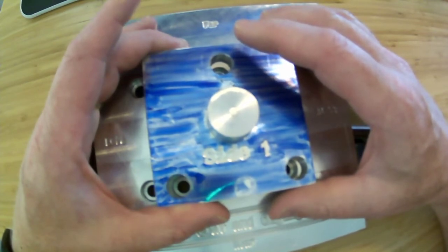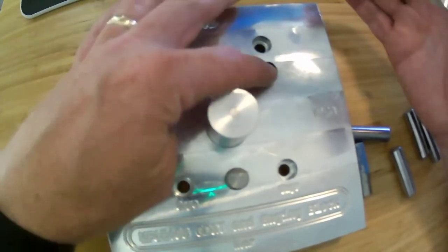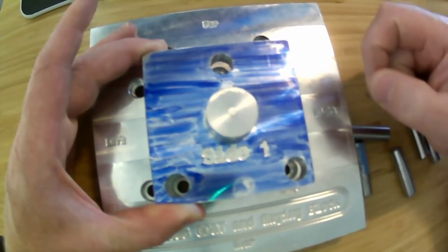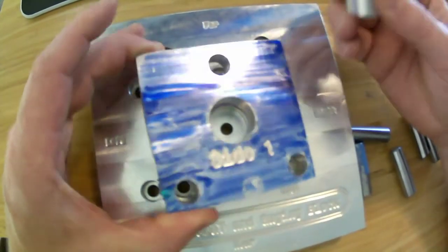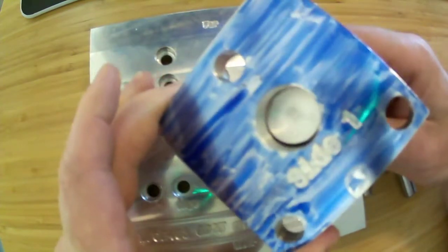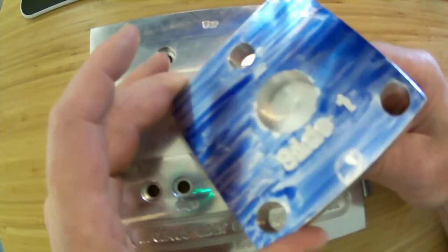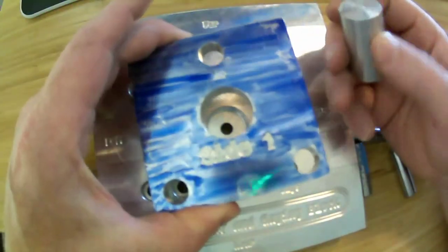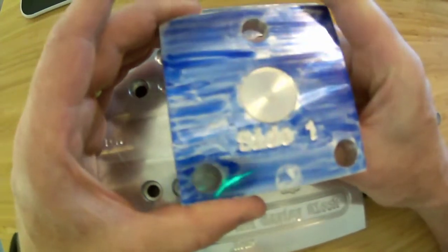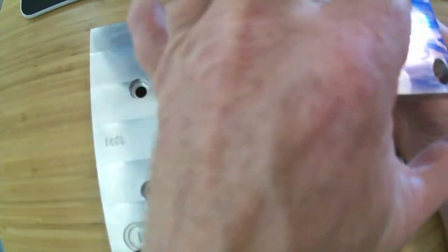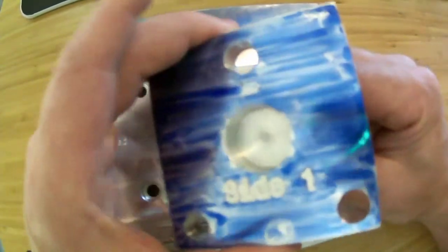I could over-constrain it. I could make it not be deterministic by putting in 3 points on this surface down here to make it so it sits down more evenly, but it would be way over-constrained by this cylinder. It might be that I could also take this cylinder, and if this cylinder just barely protruded into that hole, it would provide almost no limitation on the moments around X and Y. The only thing that it would do is limit translation in X and Y. And so if I had a little short cylinder here that just barely came into the bottom of the hole, it would no longer be over-constrained because I would have removed 3 degrees of freedom here, 2 more here, and the only one that I would have left would be the rotation around Z.